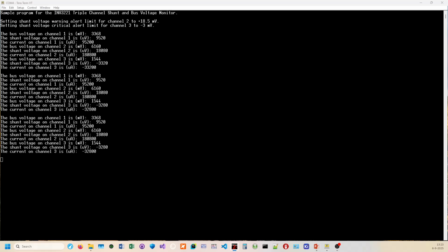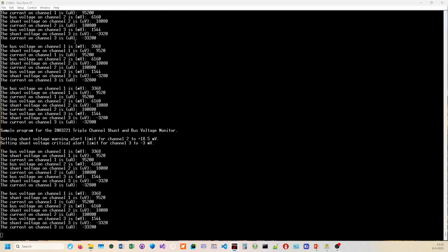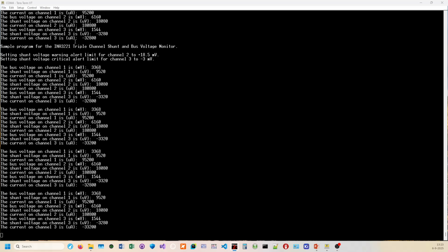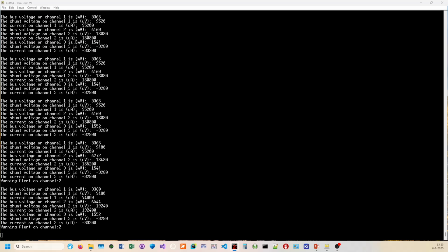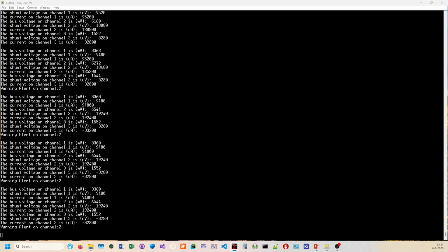So let's continue doing these measurements. I will first increase the voltage on channel 2, and now you see I get a warning alert. So I will reset. And why do I get a warning alert? Because the current is 192 milliamps, which is more than the 185 that I just set up.